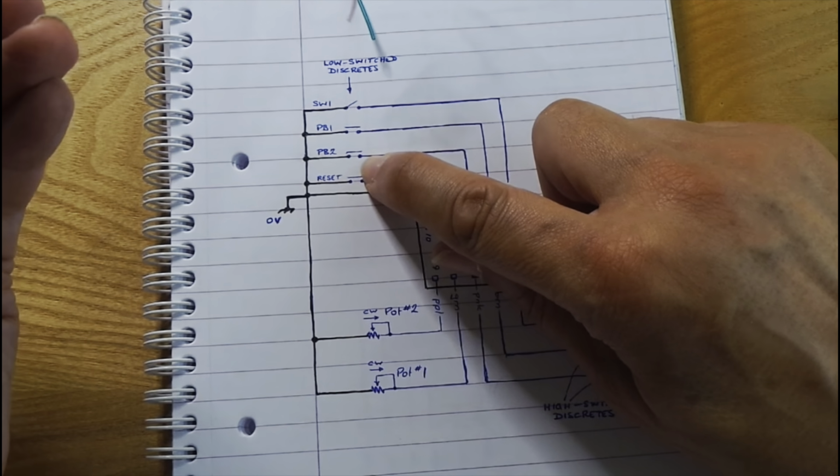Now, any of these pins which you don't use, you can easily just remove the pins by, if you look at this connector closely here, you see that each pin has a little plastic tab, and if you just get a very small screwdriver and raise that plastic tab, you can pull out the wires for unused connections. So that will make the harness a little less confusing if you pull out the ones that you don't need.